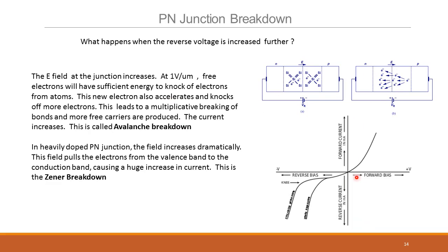So just looking at the reverse thing, right? So this is your avalanche breakdown. Avalanche breakdown happens when the doping densities are not very large. But if the doping densities are large, you know that the internal electric field actually is already high. On top of it, you give it a little bit more push, you'll have a Zener breakdown. This is for a heavily doped semiconductor piece of PN junction.